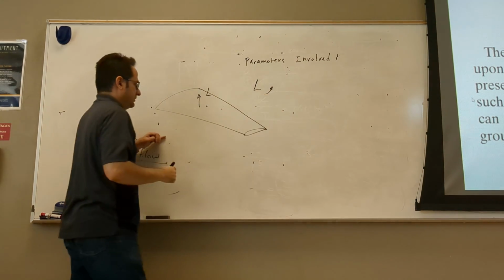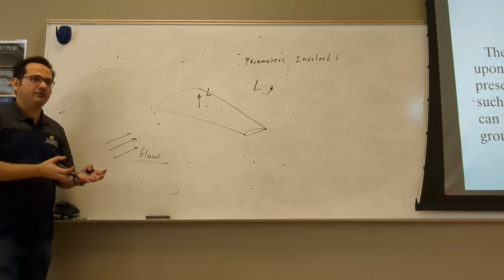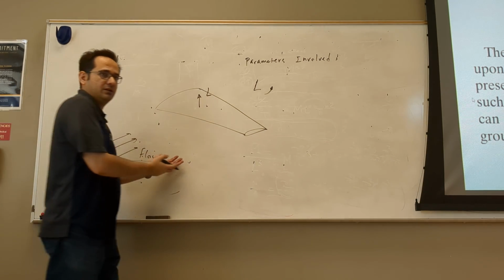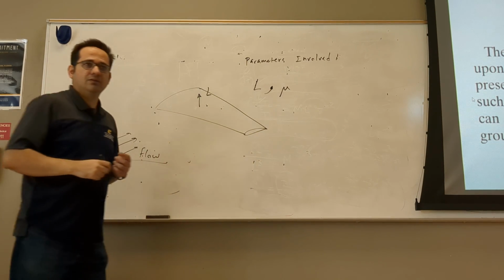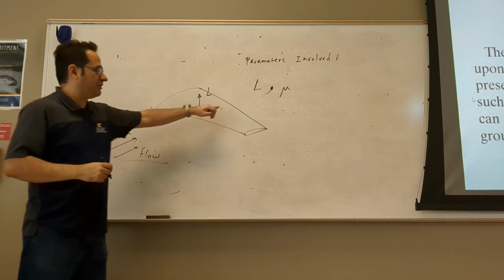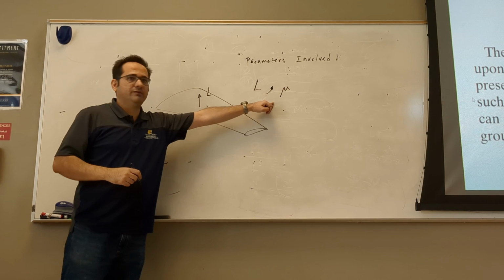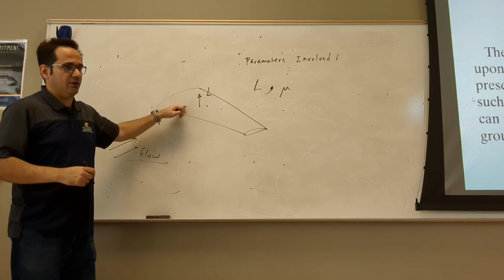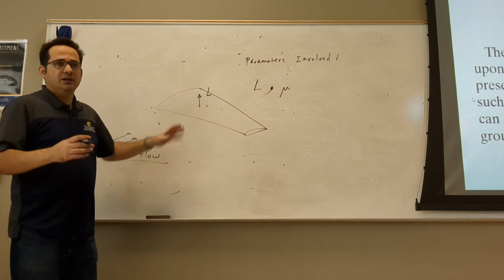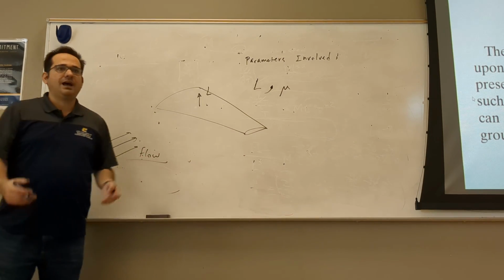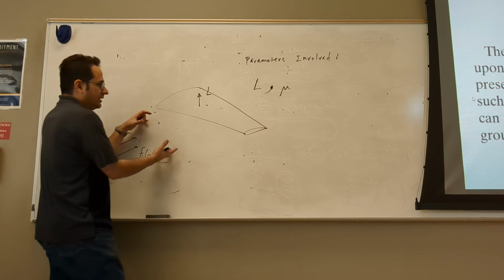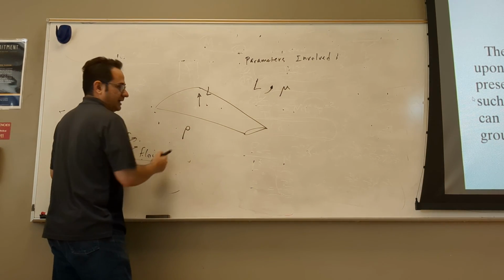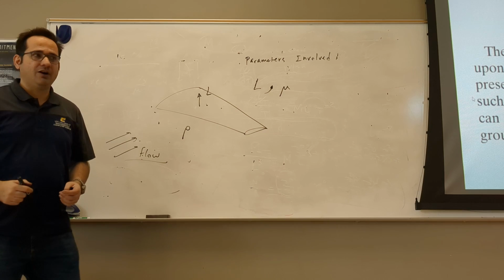The other one is what? I know the lift will increase if the flow is viscous, right? Or decrease. So one is viscosity. How do you know that? Well, in fact, viscosity is very small, the effect of viscosity on the lift is very, very small. It's more on the drag. But the way you know that, you just go to the lab and put this in the wind tunnel and test it. You put a more dense fluid, and you see the lift increases, right?